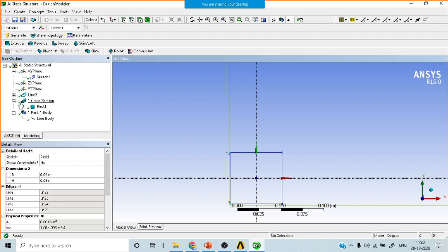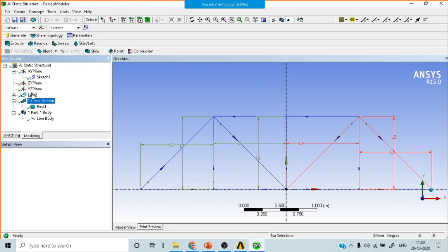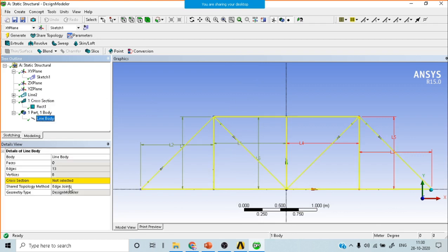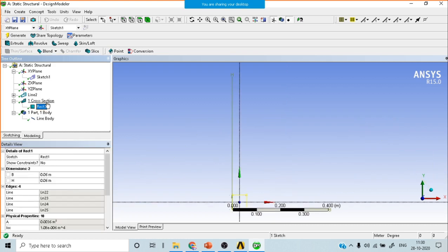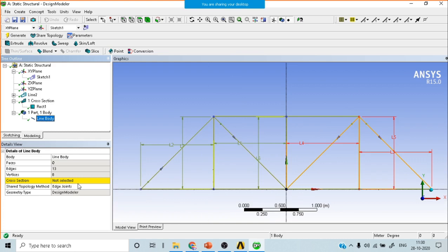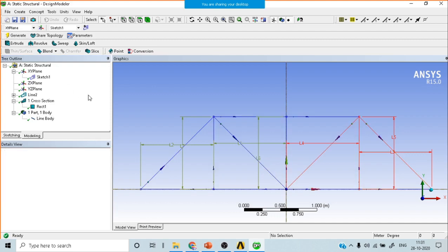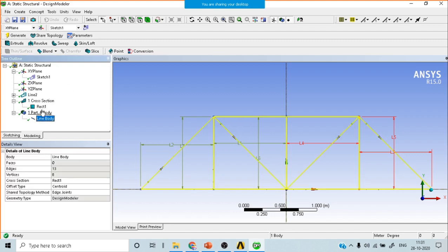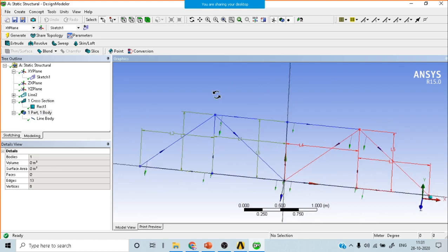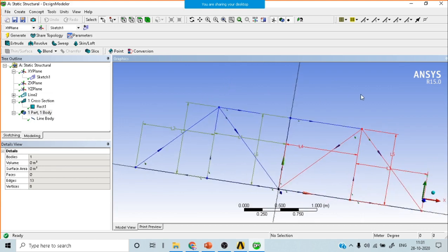Okay. So once I define this section, I need to assign this line with that particular section. Here I have given the name as rectangular. Likewise, I can define a number of cross sections. Now I can select the cross rectangle here, and then I will say generate once again. It has now assigned this. So this way we created an entire model for it.